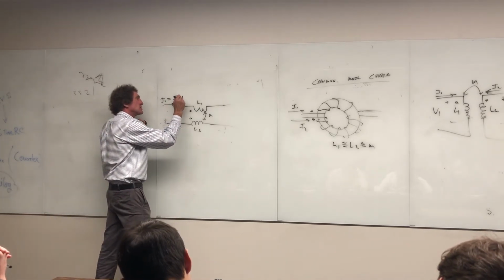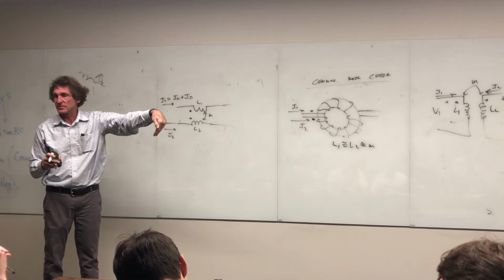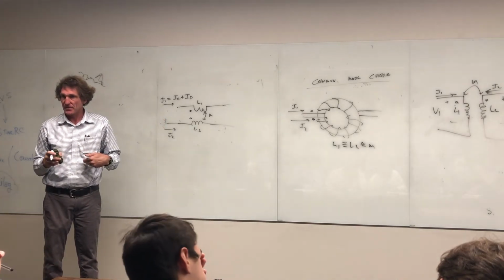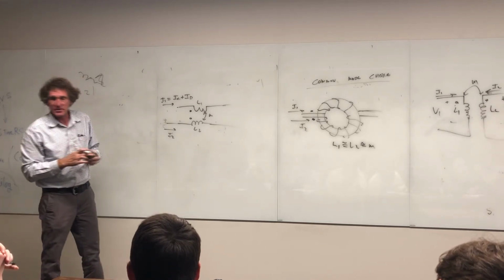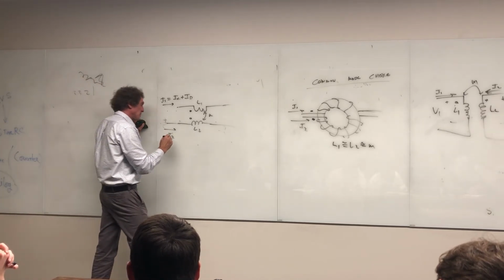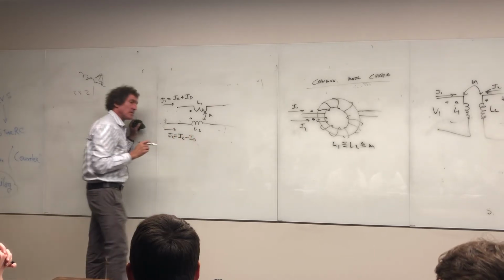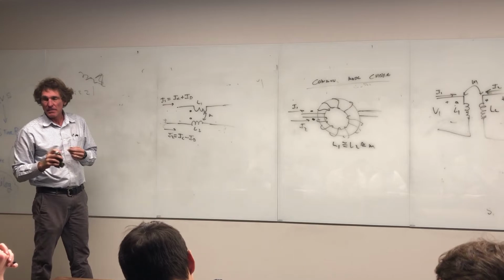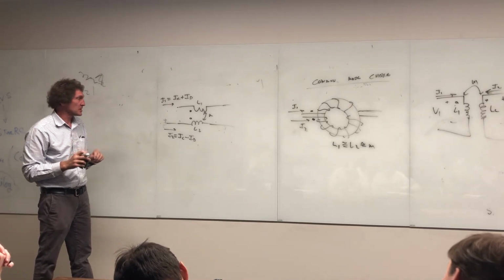But it also has a differential current. Now the differential current is the one you want. That's the one that goes down and comes back. Same magnitude, opposite direction. Do you follow me? You don't know what the values of these are yet. Here in I2 you have I common, but it's minus I differential. All right? And again, you don't know what common is, you don't know what differential is.